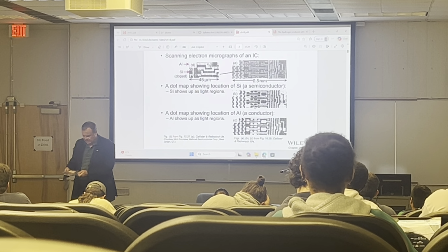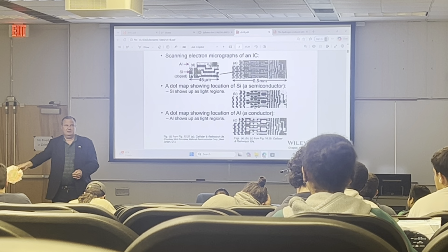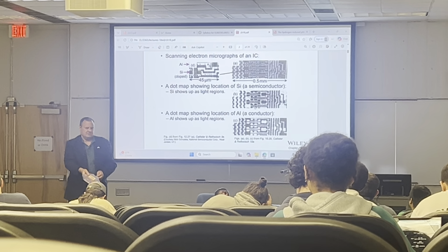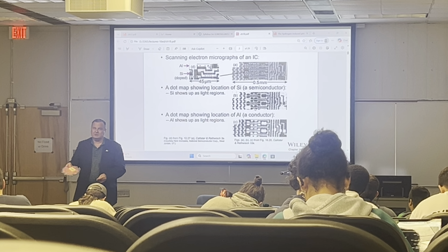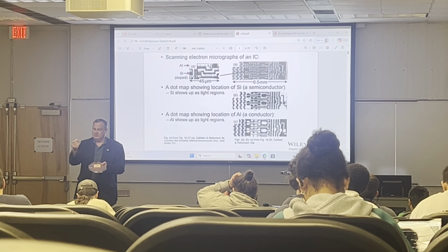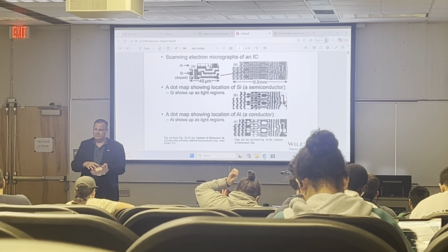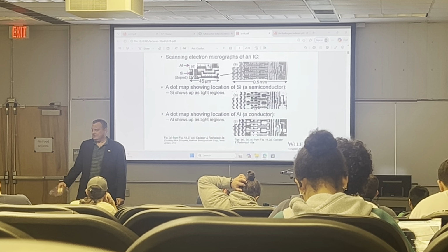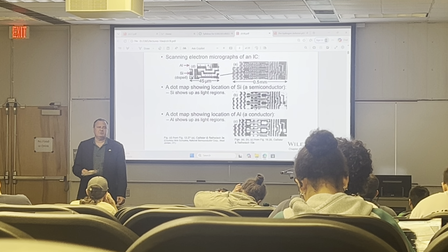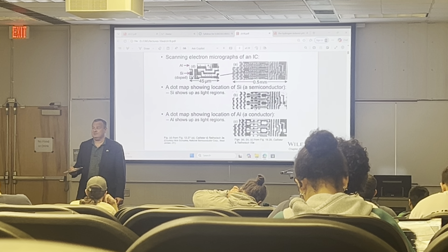And you can see this wafer has fingerprints, okay? And over time, these fingerprints turned tarnished because of the chemical reaction of the oil and moisture from the hands with the copper material. It was a reject wafer like this. And after I put this wafer, I got 23 defects.